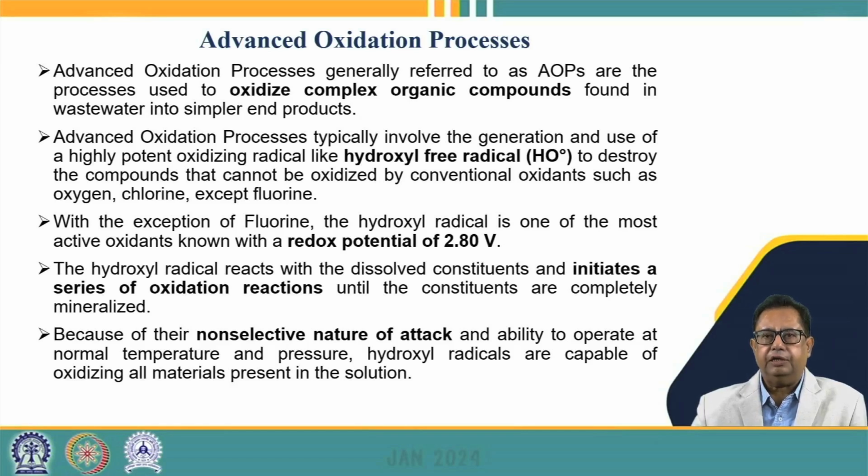Hydroxyl radical then reacts with different constituents, and they can initiate a number of oxidation reactions so that the constituents can be completely mineralized, converted into carbon dioxide and water. But they have a non-selective approach, that is, they cannot target a particular compound, and whatever compounds can be oxidized will be oxidized by the dot OH radical, and they cannot select a certain compound and oxidize it.